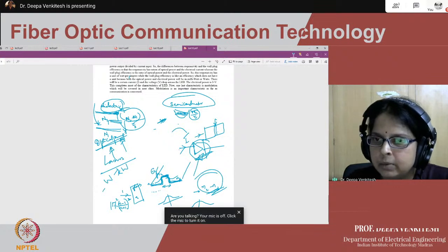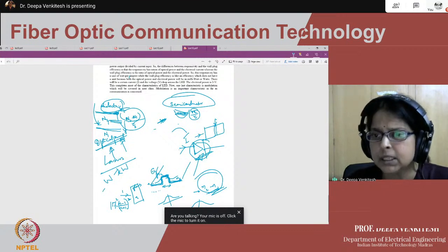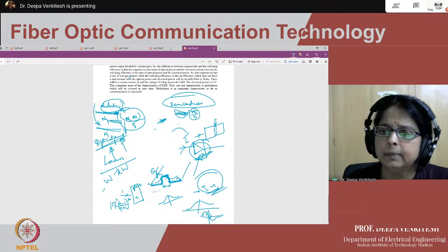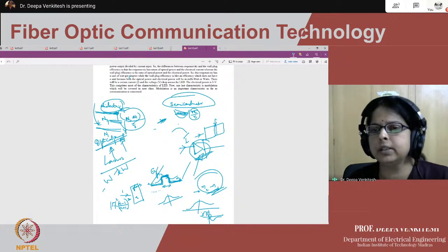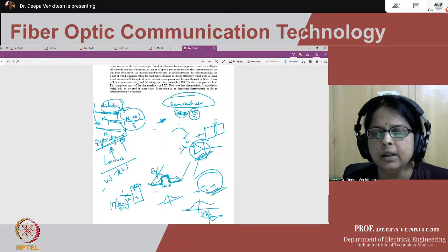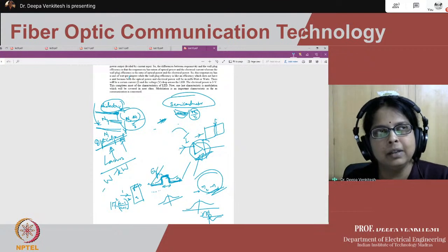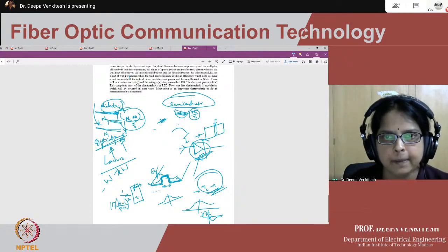Whereas Nyquist shaping is actually to do the time domain shaping such that you are able to transport the given information in the lowest possible bandwidth. Again, probably lecture 8 had that. Let's see.